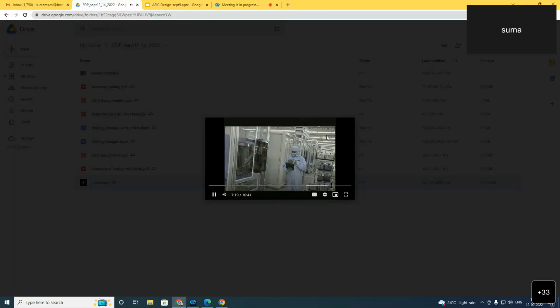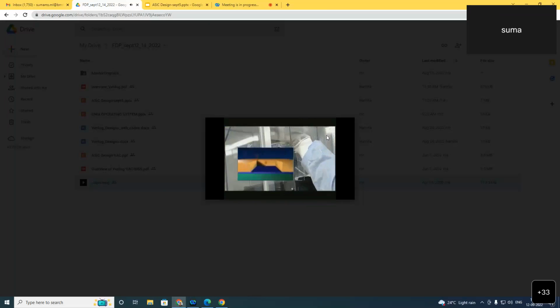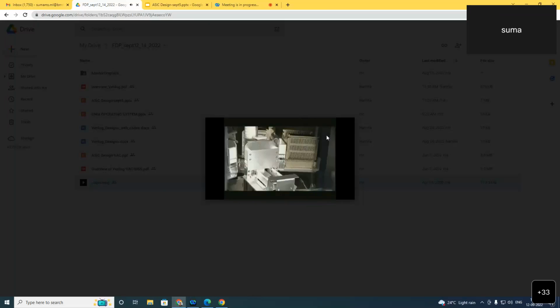In the ion implanter, specific atoms can be shot into the unprotected areas of the silicon to give them a positive or negative conductivity. This is done incredibly accurately. For example, one atom in 100,000 silicon atoms.